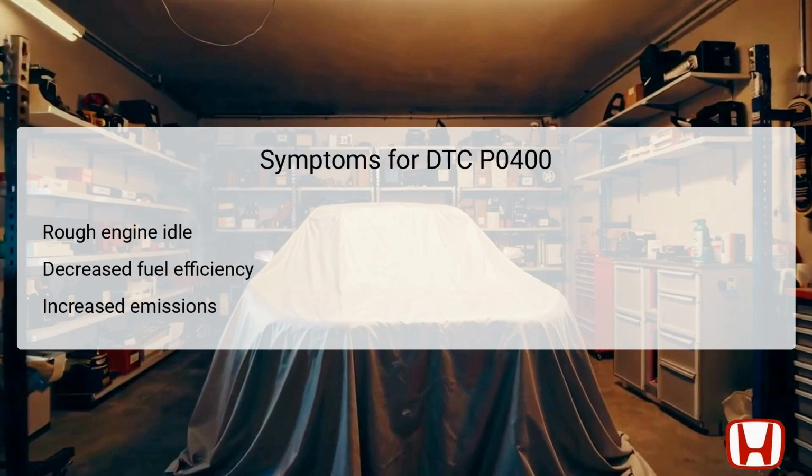with emission standards. Symptoms associated with DTC P0400 can significantly affect the vehicle's overall performance. A rough engine idle is often one of the first noticeable signs, indicating that the engine is struggling to maintain stable combustion due to improper exhaust gas recirculation.